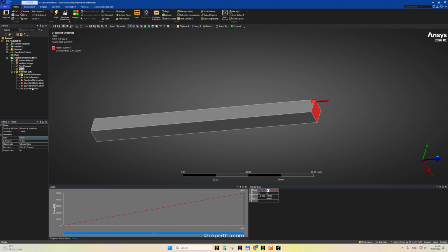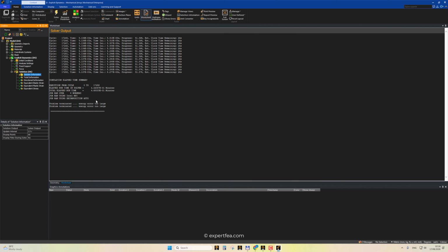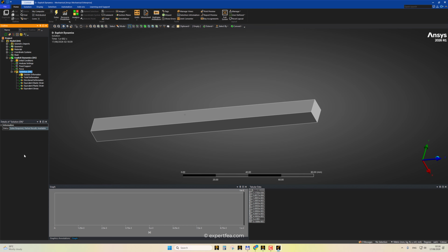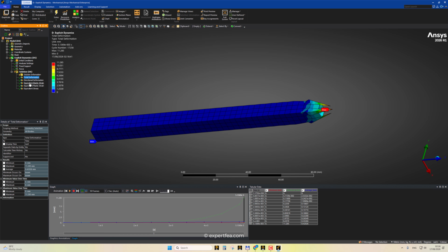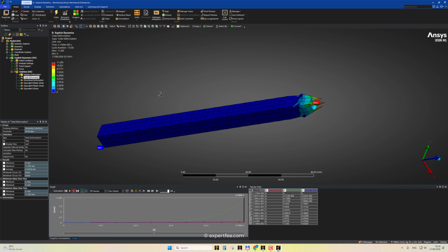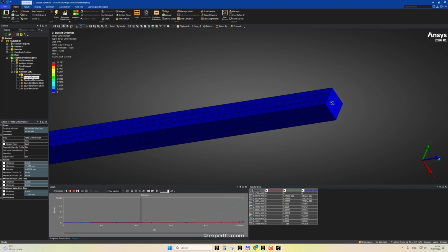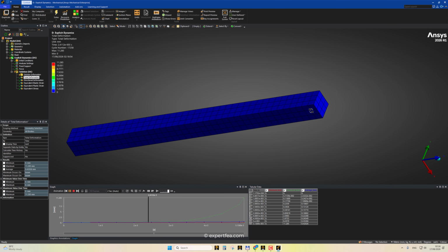Let me show it to you. Firstly, I think we have an error. Yeah, energy error too large. So, there is something. As I told you, there is a shock, and the force is applied only in this area. But it's a sudden appliance, a sudden occurrence of force.